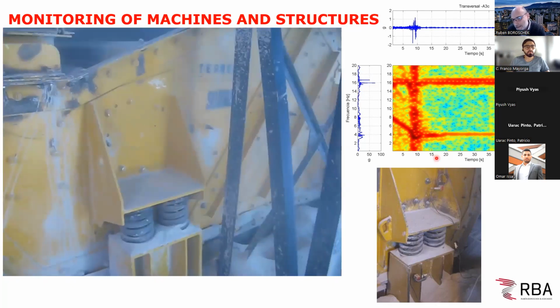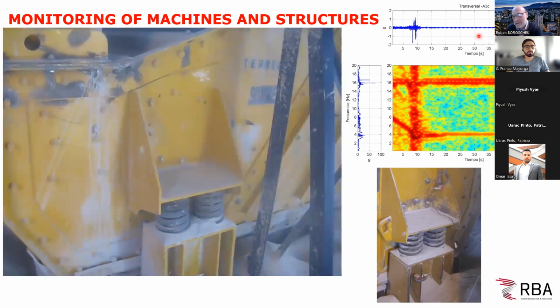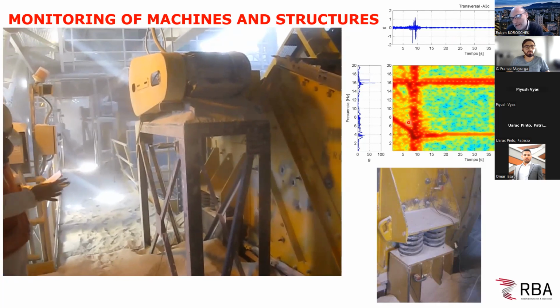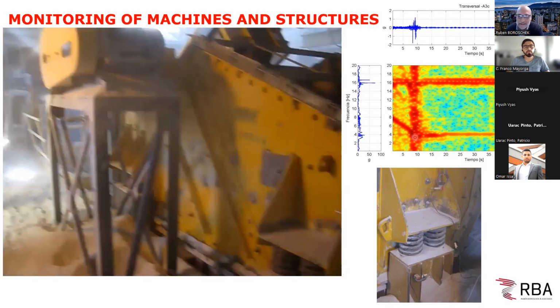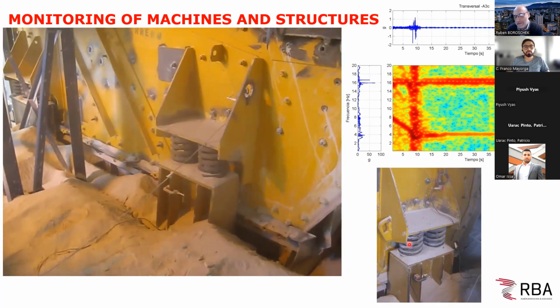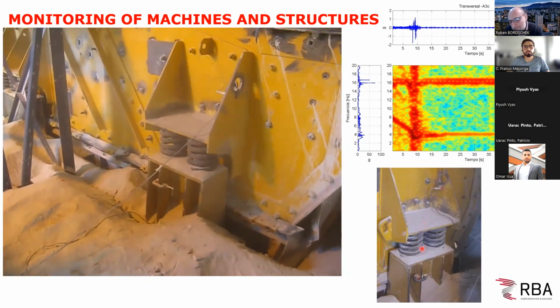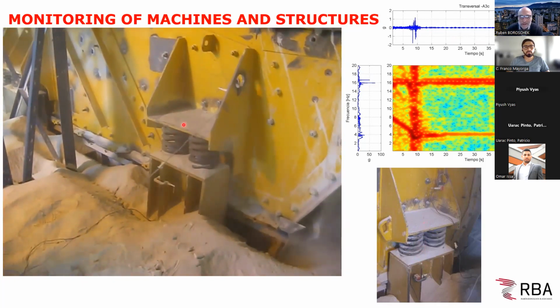So what we do here, we put, for example, accelerometers. We do, again, a time frequency decomposition. I can explain how we do it later in the questionnaire part, just concepts now. And we get the intensity of vibration as the darker color here, so we get the resonance value, and from the decay we get the damping, and from the relative motions between the two surfaces of the spring we get the loads on the spring during resonance, for example.